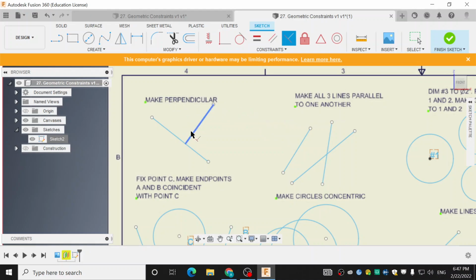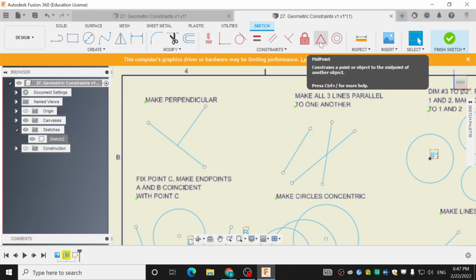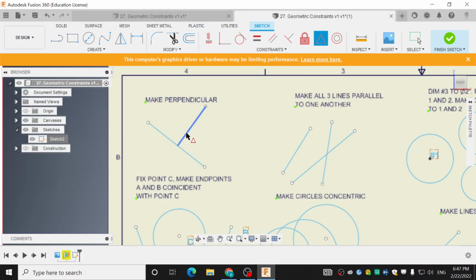So while we're still on the shape, we're going to do another one. If you notice, this shape does move up and down. There is no constraint. We want to try to generally put it in the middle. So we're going to use this one up here. This is called the midpoint constraint. This is going to allow us to put a point in the middle of a line. So we're going to click on it, and we're going to hover over this part right here, and wait for a point. Now if you notice, if you take your mouse off, there's only 3 points, because this point that intersects the two isn't shown by default, so you have to go over there and find it. So you want to find this point, click on it, and then click on the line, and it's going to snap it directly in the middle.